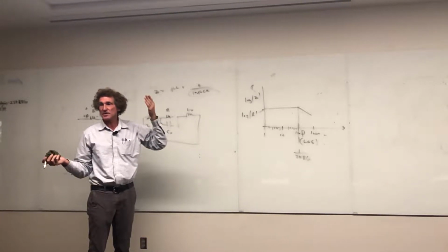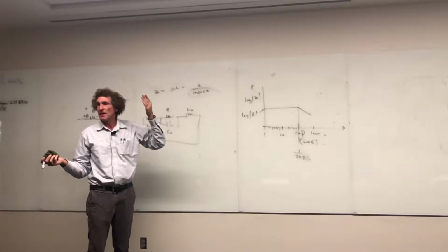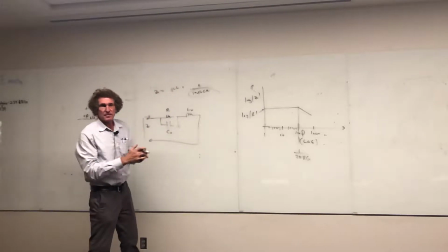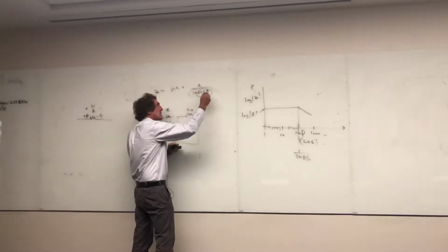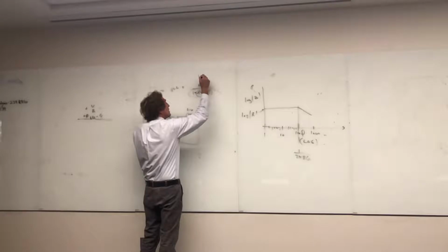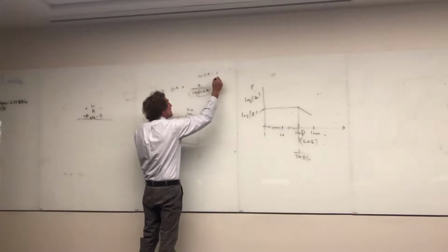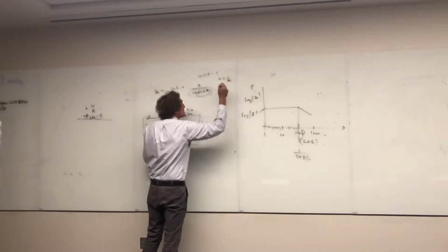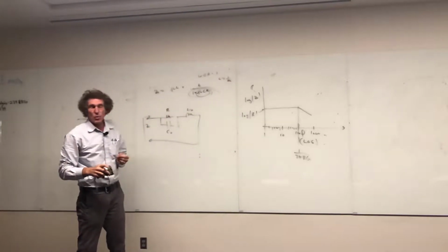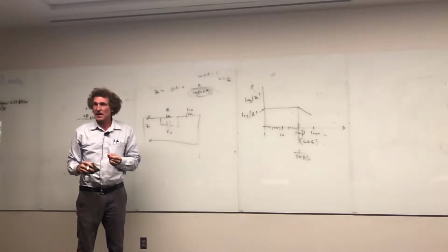Do you all follow me in this class? You remember this from signals and systems? And from, I don't know if you had it in circuits or not. How many do? All right, so that's the reason I put it this way. I can take a look when omega times C times R equals 1, and that's really going to be when omega is equal to 1 over RC, or f is going to be equal to 1 over 2 pi RC. Does everybody see this, class?